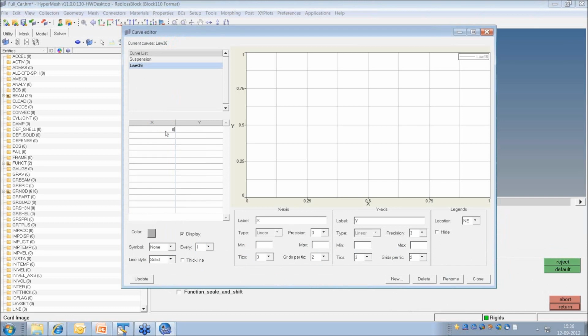So at 0 it is 200. This is one important point from the solver perspective. Here what I'm telling is at 0 plastic strain, my yield is, say, 200. So my curve has to start from a positive yield. It has to start from something like this. Okay.